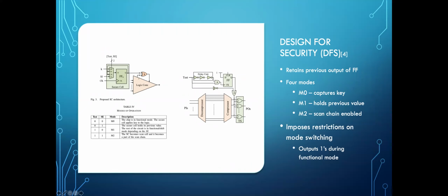Mode 1 is when these are operating functionally and the outputs are able to be tested. And mode 0 is used in the secure site, usually the design house, and that's where the secret keys are programmed. So this prevents any multi-cycle readings that would usually reveal sensitive information regarding the secret key. This is a typo, it should be 3 modes.